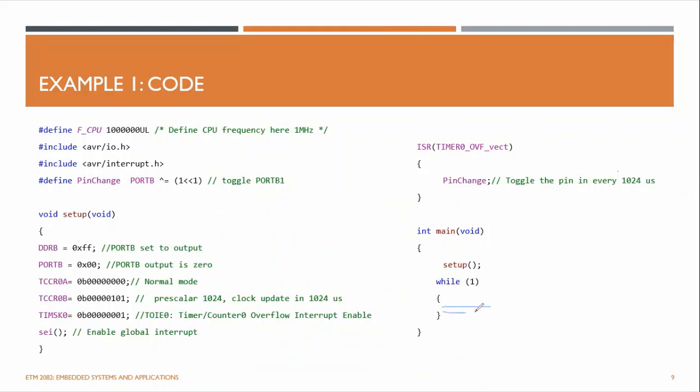You can do anything here. Whenever the interrupt is generated, only then you go there and do this work, because it is just a simple single line command. If you use a delay to do this, you are just being busy in the delay function without doing anything, and you are not going to execute the other lines below.